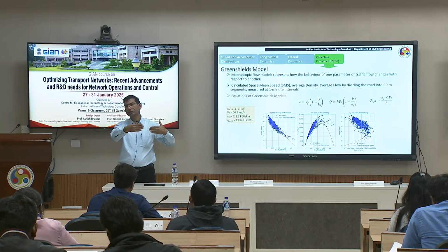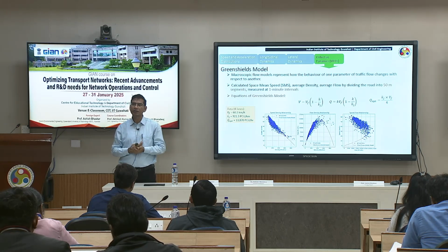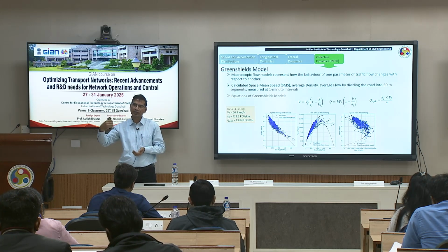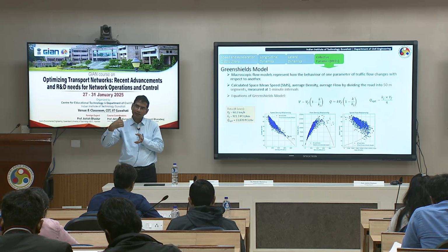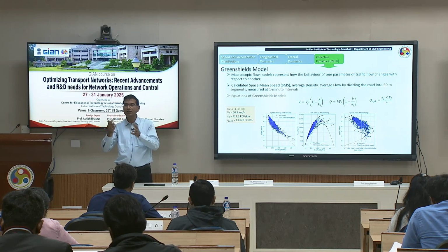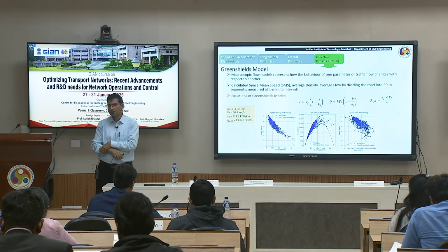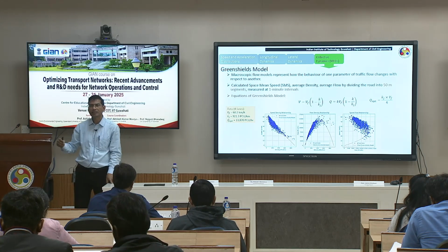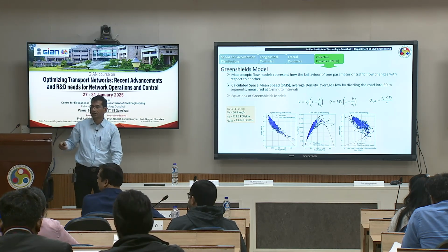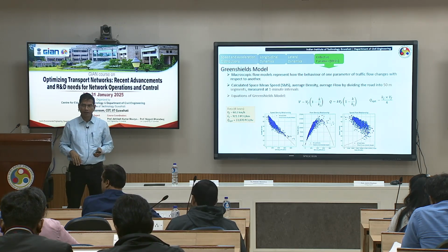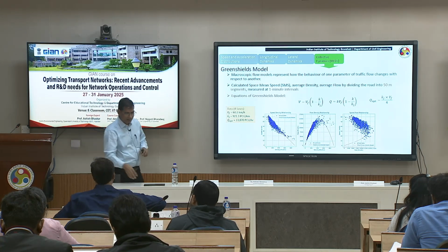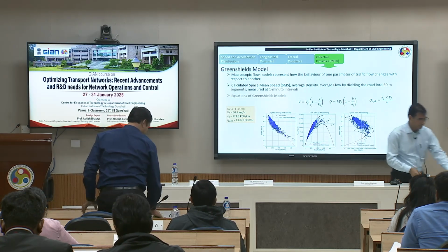But if you had congestion condition data here, it might work out to simulate that kind of condition: in congestion, how much gap they maintain, lateral gap they maintain. Then you can apply some kind of gap acceptance formulation for shifting laterally, and then you can simulate. So this data might help to a certain extent. Okay. Yeah, I think one issue is that in India, especially, many of the transitions happen in the transition zone area.